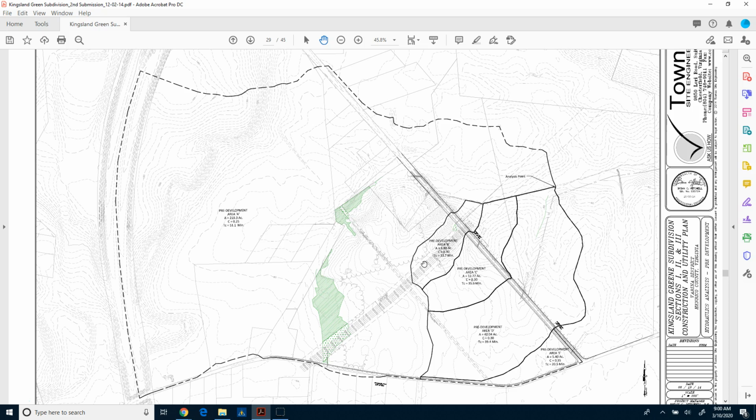So some of that water is going to evaporate, some of it's going to go into the soils, and some of it's going to run off. So it's going to go into the streams and into existing other sewer systems, or storm sewer systems. So basically, what you have to do is analyze the site and say, okay, before we do any development, this is what our runoff is going to be.